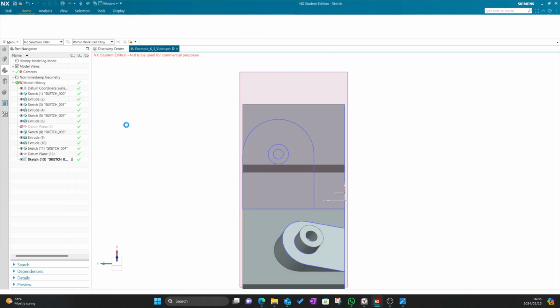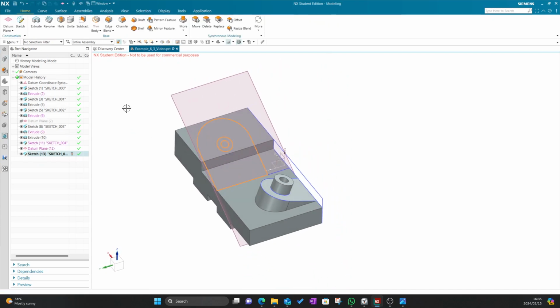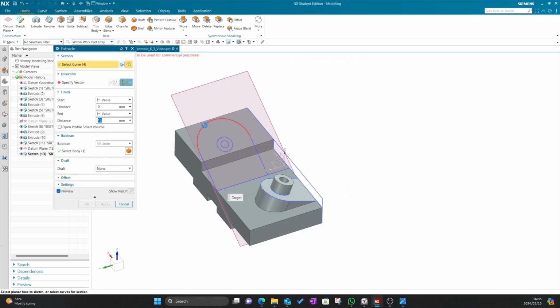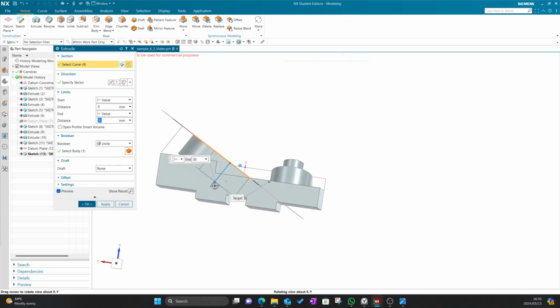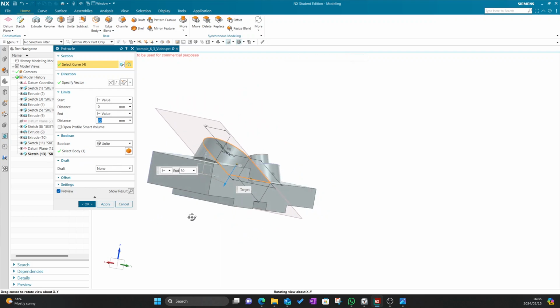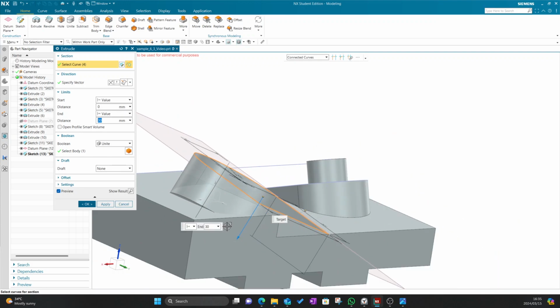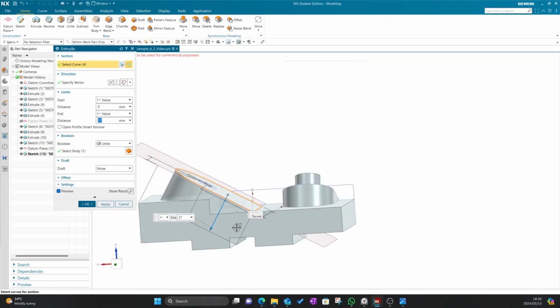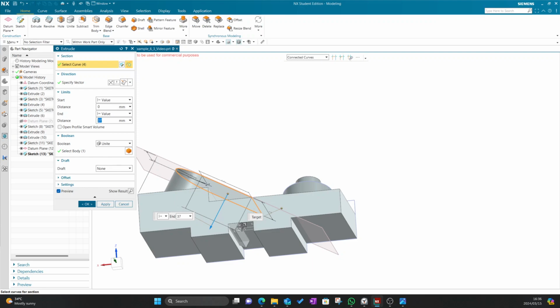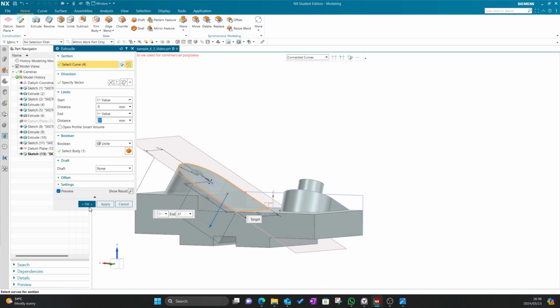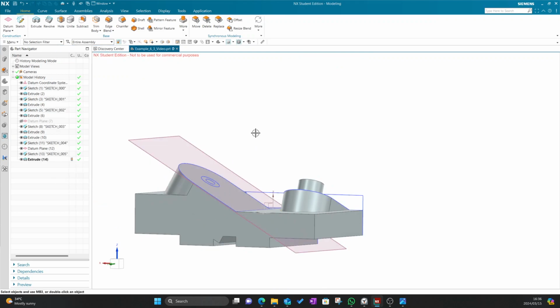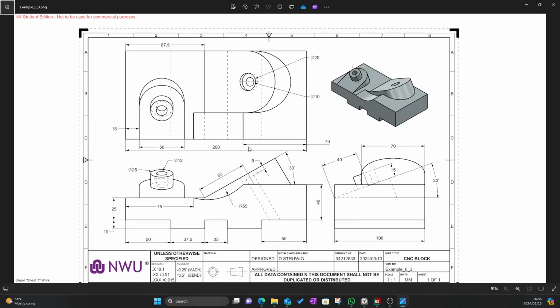So I'm going to finish this sketch, and now, yeah, the process is the same. Using extrude, I'm first going to extrude this feature downwards with a unite, and let's just make sure. So you'll see I need to extrude it now until that feature is entirely into the block, so until there about. But now you'll see it starts getting outside at the bottom, but that's not a problem. We'll just trim that. So I'll show you how now. So clicking OK, we have a united feature.